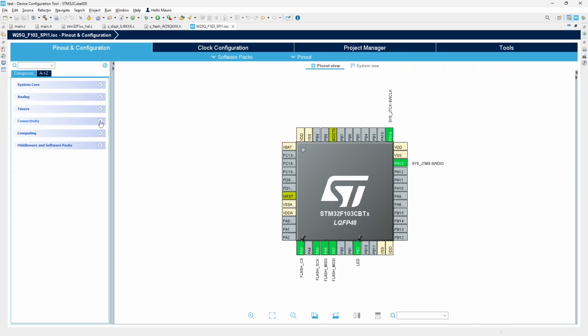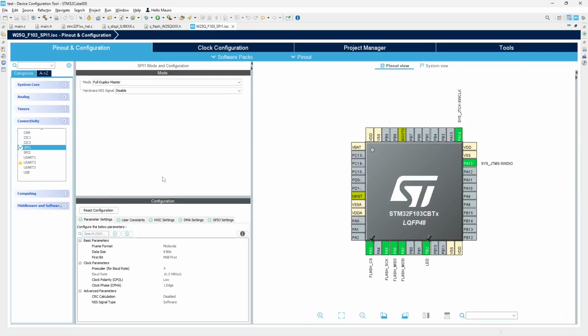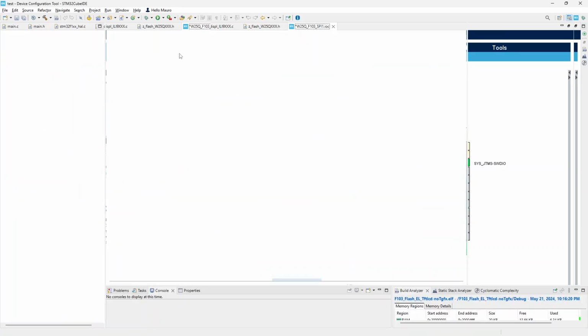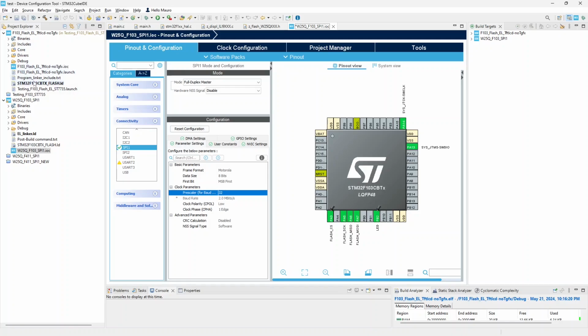Keep low the SPI port speed on the external loader. After all, you don't need it on runtime. It doesn't affect your final project performance. And this way, you will have an easy SPI flash memory handling in setting up and testing the project.